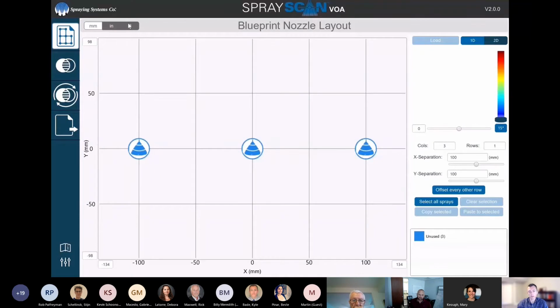Absolutely. If you're doing quality control checks, to be able to not replace a nozzle too early or too late, both of those are advantageous. So you can really nail down, right, where is that maintenance window that's optimal. And Kyle, not to get too much into the detail, but this can be quantifiable, right, with the coefficient of variation. Yeah, absolutely. We can have thresholds that the client can look at and say, hey, at 60% correlation, and then perhaps there's something that we need to do there.